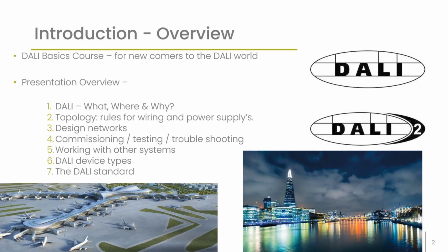Topology, rules for wiring and power supplies, and we look at a typical wiring part of it. We also look at network design. We'll take you on to commissioning, testing, troubleshooting. We look at working with other systems, and in particular, I do a live demonstration of ETS and how to set up some of our Dali gateways in ETS, and also the Dali addressing tools that come with those products. So we'll have a look at those. We'll have a look at what Dali device types are and the Dali standard.